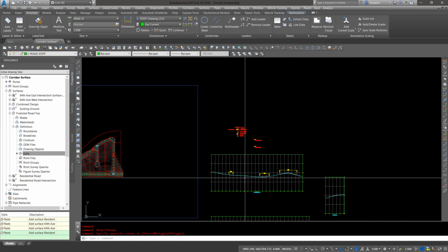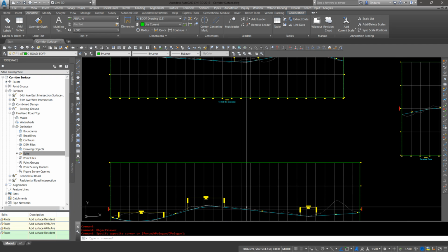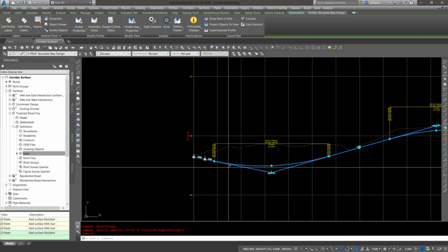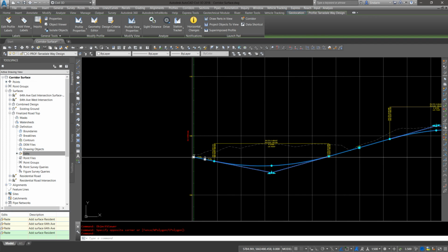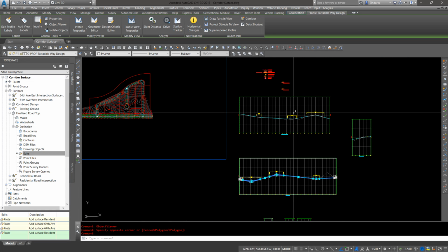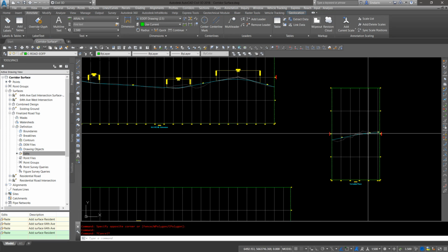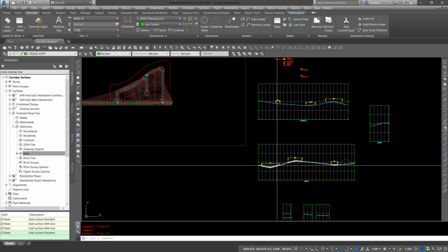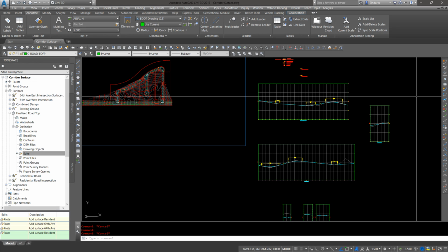And one last look at the profiles, just to show you what Civil 3D does. If we look at Taradale Way, I can now click on this and we have 2 locks on the end. So this means Civil 3D has joined the roads together. These roads are combined to this road up here. This one here is locked because it's combined with this one. So Civil 3D locks it for us. We can't modify those too much. If we do, we'll break the link. So again, that's just creating a corridor. We'll go diagnosing the issues in another video.